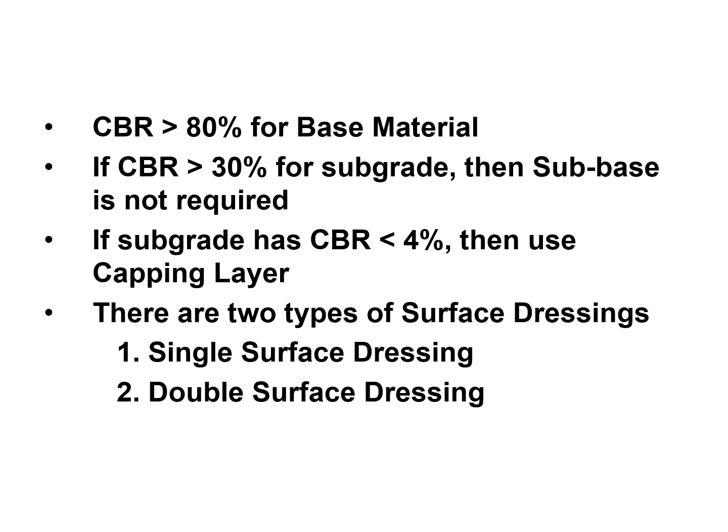Either we can use the surface dressing, or we can use the flexible bituminous surfacing, or you can say the pre-mixed bituminous material. And the third, which is the most rational one, is the proper surface course, which will consist of wearing course, and just beneath the wearing course we will have the intermediate or binder course.